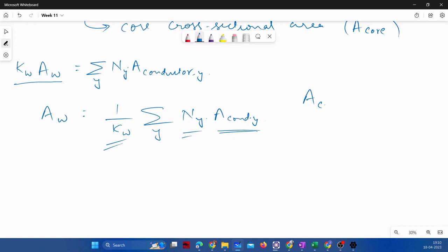And area of conductor, you know, that is I RMS by J max. So J max you will have to decide initially, if you know the rating of the material. If you are going for natural cooling, you can decide J max is equal to 5 ampere per mm square. So J max will be fixed beforehand, and area...